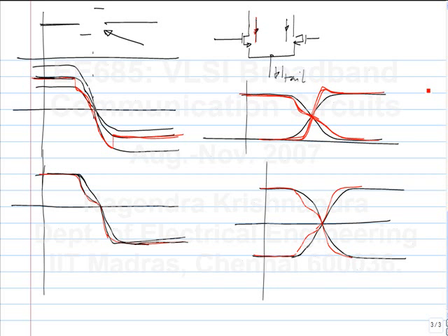So, are you saying this as a method of testing the nonlinearity? No, because in this case, how do you apply a sine wave? So what happens is, yeah, it is true. In the ideal case, that's one of the ways you test it. But let's say the spectral density of whatever you are transmitting looks something like this. Because of nonlinearity, some parts will intermodulate and fall onto some other parts, and the shape will not be maintained. That's all.